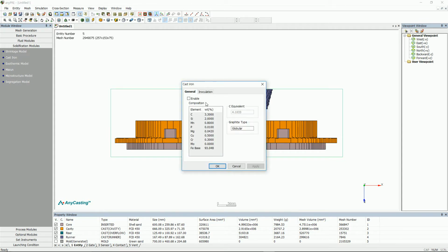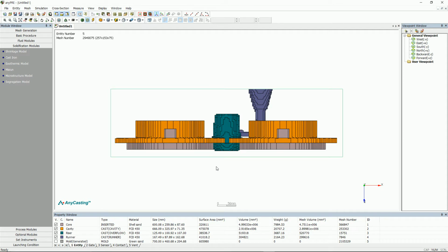When this function is used, the mechanical properties and phase fraction will be predicted depending on the amount of alloy element. Also, when this option is selected, regardless of the end condition, the simulation will end only after the temperature is cooled until 300 degrees.